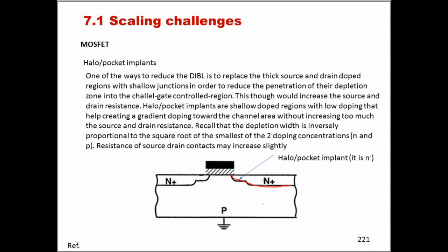So this is a very nice technique to reduce the depletion regions in the close proximity of the channel, and it has been effectively used for quite some time, and still today is used, to prevent any negative effect due to DIBL in the channel area.